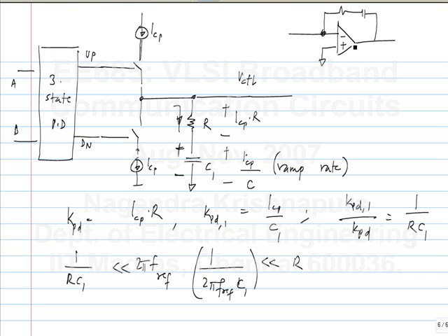Typically, you use a very simple circuit here because these circuits also add noise. You don't want to make them very complicated. That's why you use the simplest possible thing. In some cases you may have to use more complicated stuff because the size of these components may become unmanageable when you try to realize it on an integrated circuit. In that case, you may go for some fancy circuit which perhaps adds noise but reduces the size of the circuit.